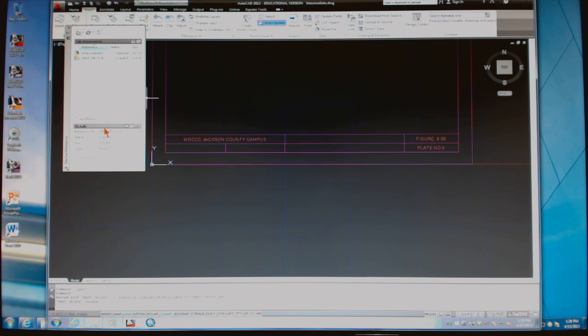But then is there not some information that cannot be the same on every drawing? Page number? Person who drew it? Sheet title? Revisions? All this kind of stuff is things that could possibly change on each and every individual sheet. So, if that's the case, then we need to get that information off of it, right? Off of the original. But you still got to have the placement of that information so it can be put on the title block very easily.